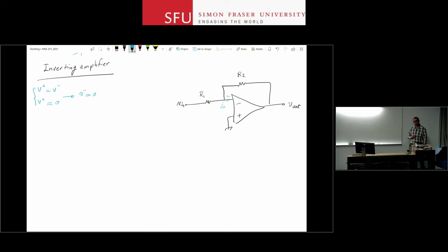The second rule says I into the op-amp terminal is 0. So a real ground would take any current or provide any current that you want depending on the rest of the circuit requirements. In here, it just provides a fixed voltage. You cannot send or receive current from that terminal. Okay, but that is good because now I can calculate this I1, let's say.